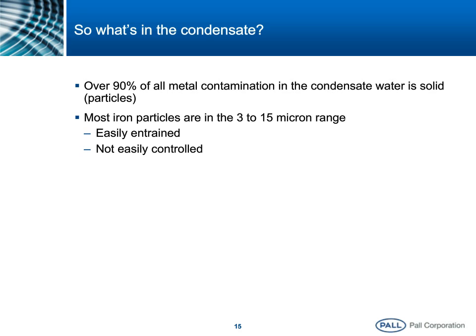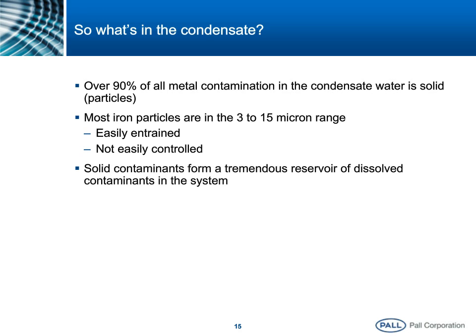As I mentioned before briefly, solid contaminants form a tremendous reservoir of potentially dissolved contaminants. So you're in a situation where as you're removing ions, let's say with your demin beds, what you have floating behind it is this huge amount of solids that basically are going to redissolve in the water in order to maintain the equilibrium, and you kind of are back to square one in that type of ionic treatment.